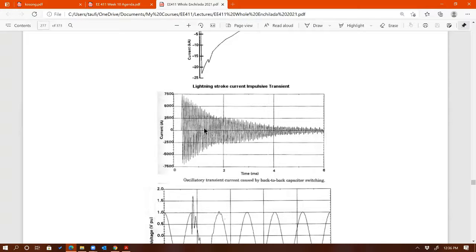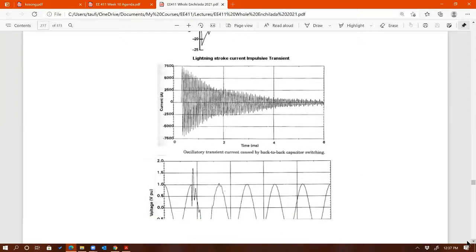And this happens due to the resonance in the system, as soon as you introduce capacitance into the power line. Now, power line is mostly inductive. So what happens if capacitor meets inductor? You learn from this class or also from 212 that they form resonance, right? So LC resonance. So that's what you're seeing there. It's LC resonance, higher frequency resonance, in the 60 hertz system.